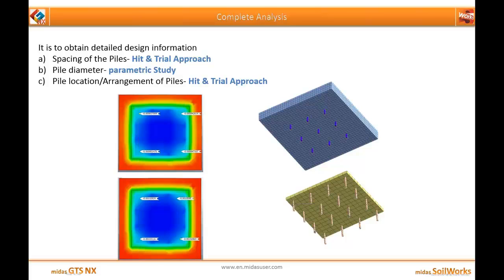So what one can do is consider two foundations, let's say with a particular raft depth and a particular pile arrangement, and similarly you can consider another raft with a different depth and a more dense pile combination, and thus you can see whether it satisfies your design criteria.